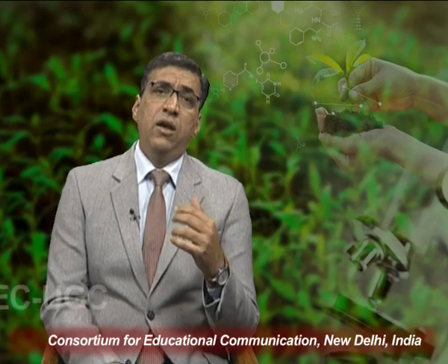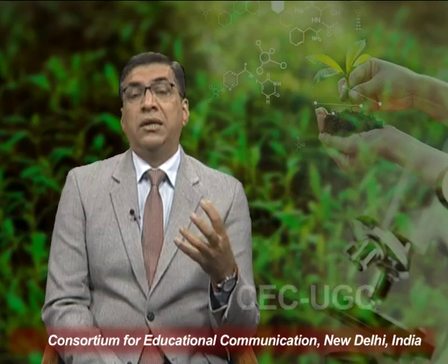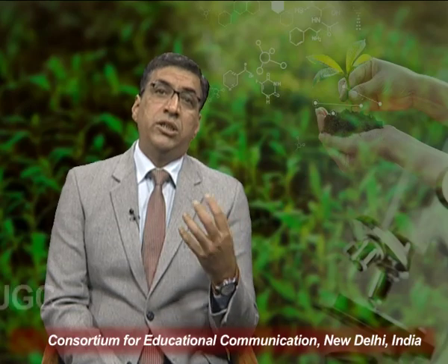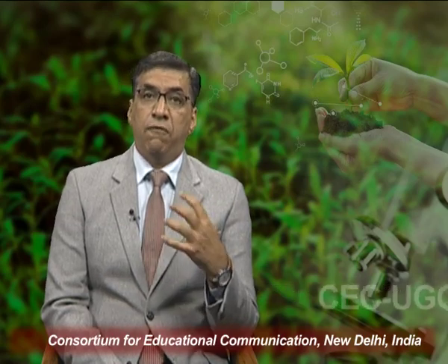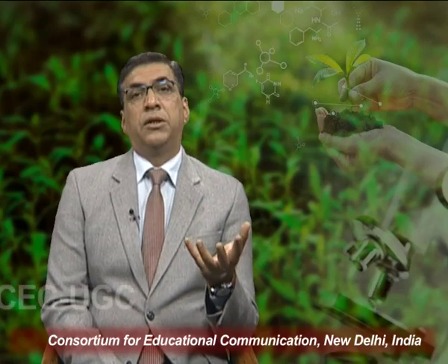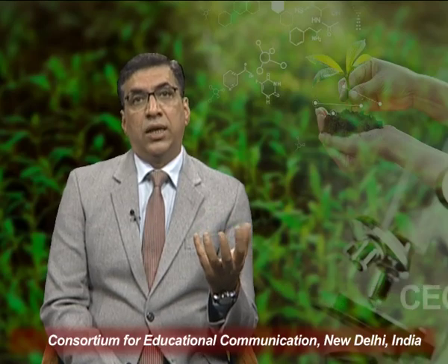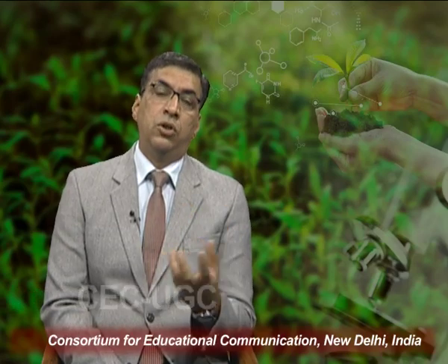So we can say that the viscosity of a culture media changes with the increase in cellular density, and it increases tremendously, steeply, if the cellular density increases beyond 10 gram per liter concentration. And once the cellular density exceeds the prescribed limit or threshold value, there is a significant increase in the viscosity, and this increase in viscosity will again inhibit the proper circulation of oxygen.